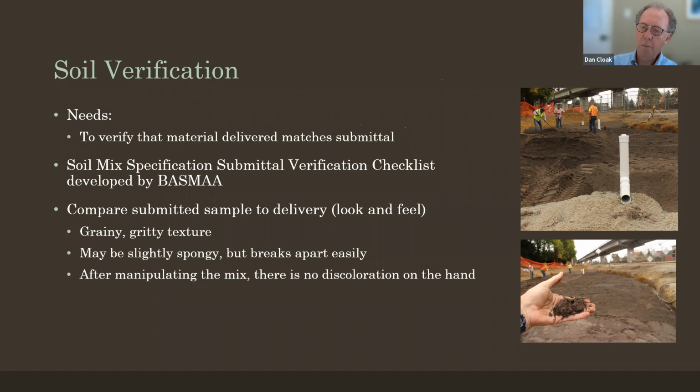And then what really shows the presence of clays is if you rub it around in your hand and then drop it and your hand is stained. That shows that you've got clays in there.